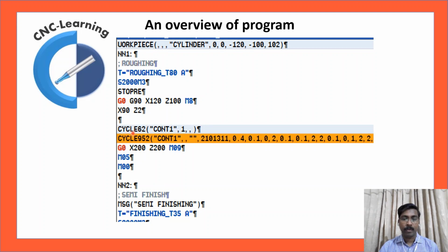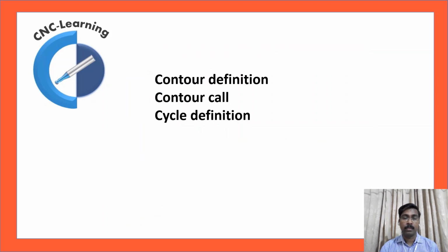Here the contour definition, contour call, and Cycle952 where the complete stock removal definition is given. So this is how the program looks like. In detail again we will see the actual program. So contour definition, contour call, and cycle definition.